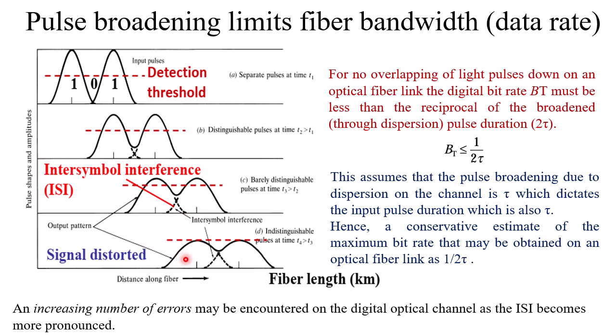If we allow the fiber to carry the signal for even more distance, it may happen that the power contained by the logic 1 pulses becomes lesser than the threshold, and the power contained in this region becomes higher than the threshold. So we have complete distortion.